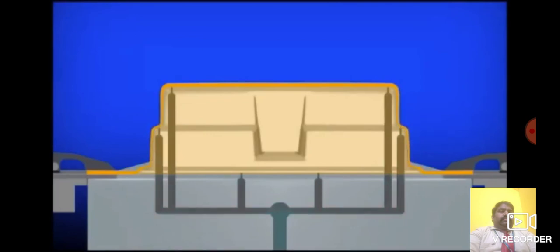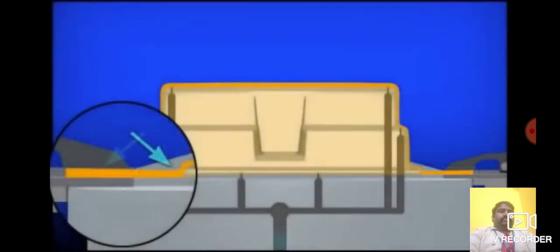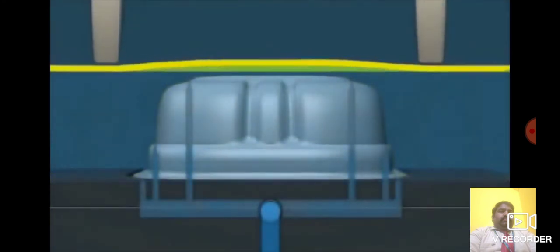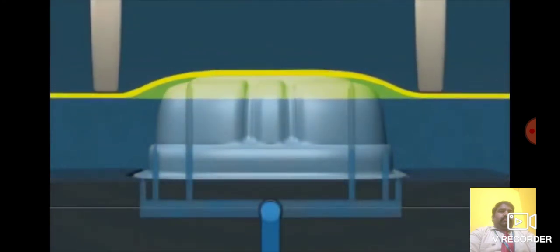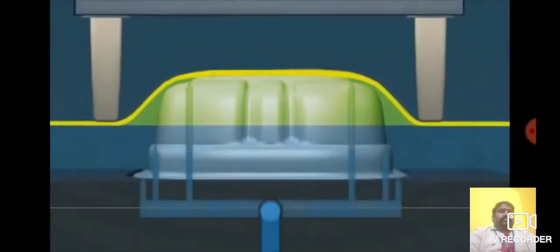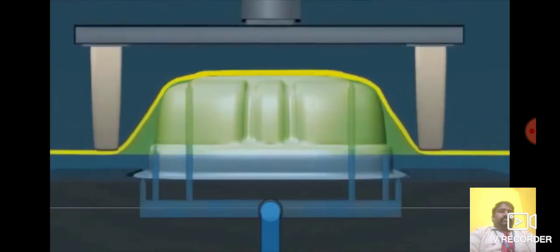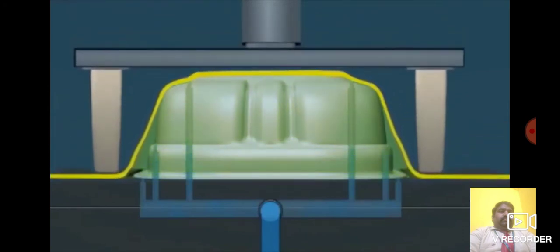The sheet distribution is the opposite of the previous mold, thick at the base of the formed part and a decreasing sidewall thickness towards the flange. The flange itself will have varying thickness, thin at the corners, thicker towards the clamp frame. Drape thermoforming is where plastic sheet is draped over a male mold. The sheet stretches as it is pulled.